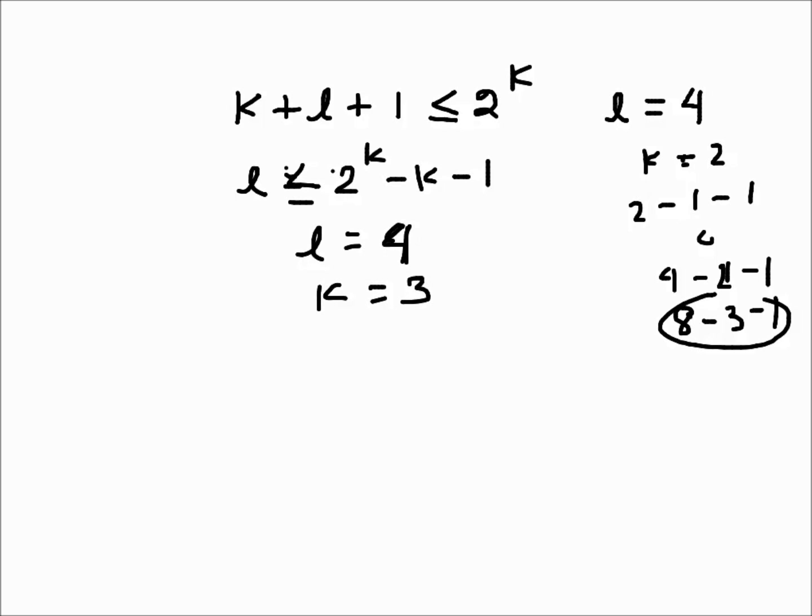Now let's see how the bits are assigned and how the total message is sent. We will have a 7-bit message. 4 of them are data bits and 3 are parity bits. So let's first write the positions: 001, 010, 011, 100, 101, 110, 111. We have 7 here: 1, 2, 3, 4, 5, 6, 7.